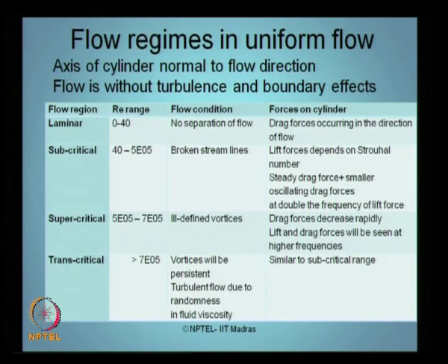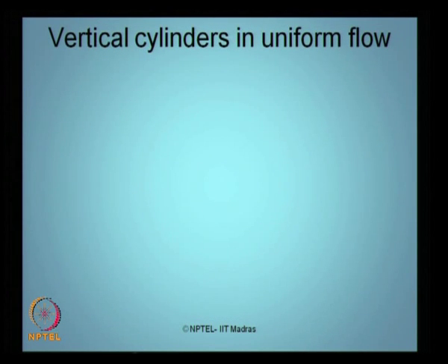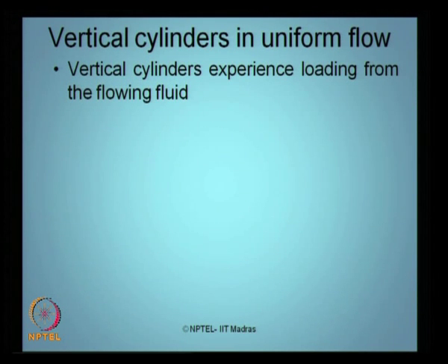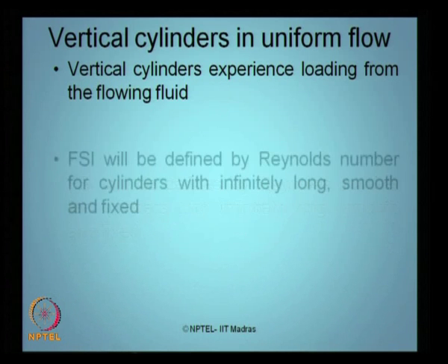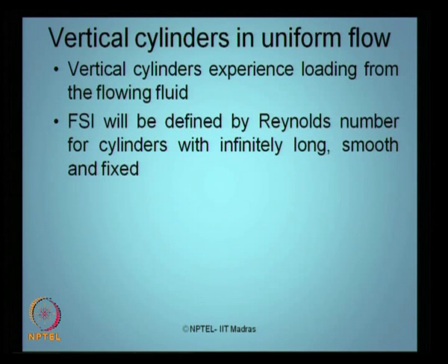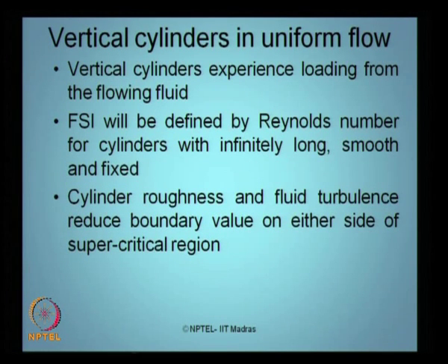Looking forward further, if we look at vertical cylinders in uniform flow, the vertical cylinders experience loading from the flowing field. Again the fluid structure interaction will be defined by the Reynolds number for the cylinders, provided the cylinders are considered to be infinitely long, smooth and fixed. So if you have infinitely long, smooth and fixed cylinders, then you can always estimate the response of these members in the FSI region purely based on Reynolds number only.